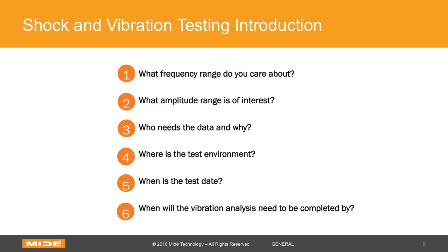Where the test environment is definitely pretty critical for the type of sensors you're going to select. It also defines where your data acquisition system and other hardware is going to live. If you're out in the field, you're going to have to make sure you have pretty rugged equipment. Whereas if you're in the lab, you're not going to be as worried about wires, and your DAQ system will probably be a computer that's just right next to whatever test setup you have. So it's critical to understand that.